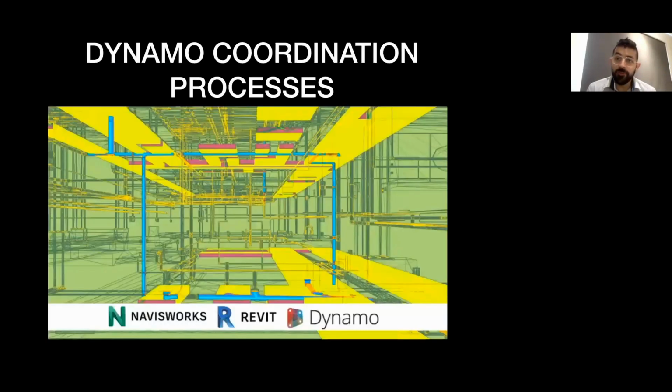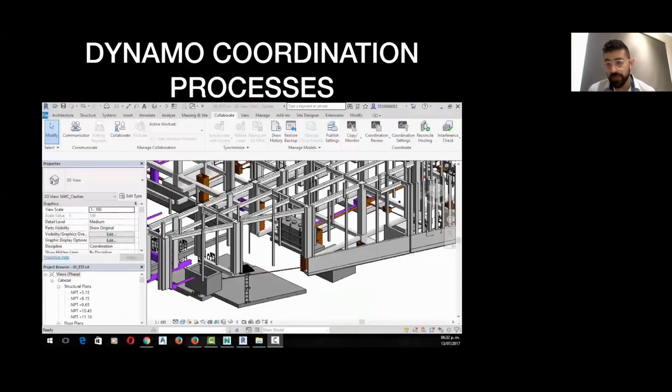And a lot of things going on between mixing Navisworks, Revit, and Dynamo patterns for clash detection. So you can use Navisworks for creating those clash points, place them, modify them with Dynamo Player, and then modify the way they are set within the structure, send reports, create the views. I mean, options are limitless.